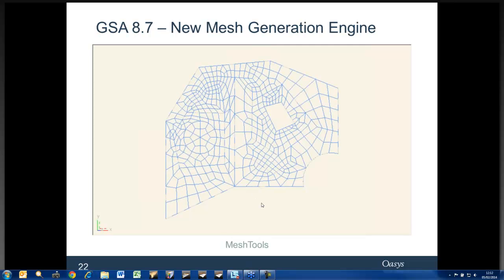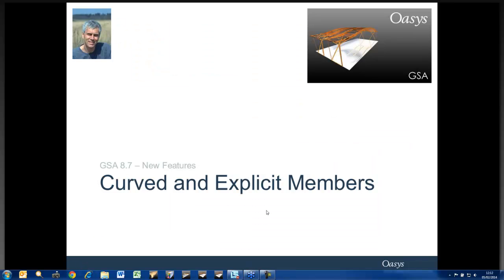Whereas the mesh tools generated version of the mesh generated for the same region is something under 500 elements, so that's a third as many elements, and all of them are in good condition. And you can see that some of the elements are tri elements in this sort of area of the mesh. So those have been introduced to improve the condition of the mesh.